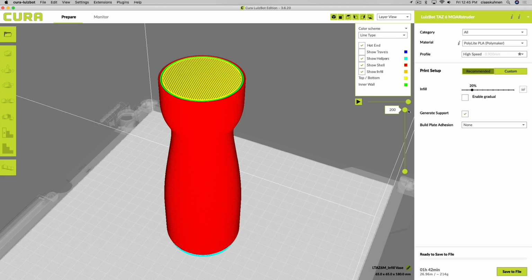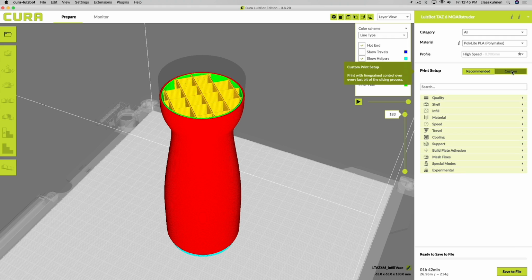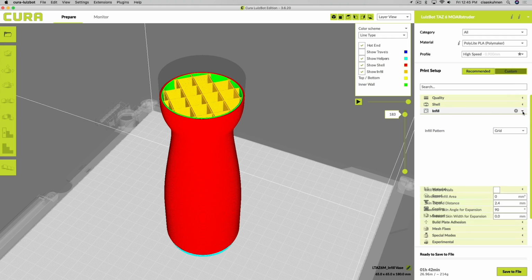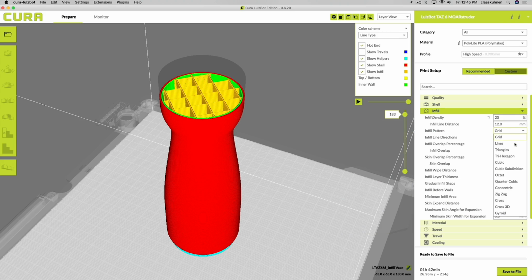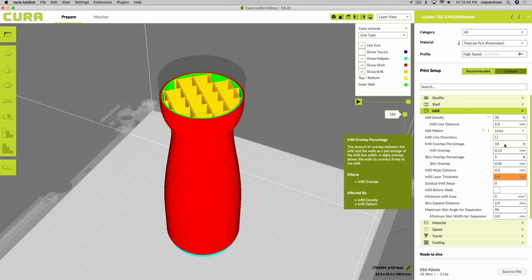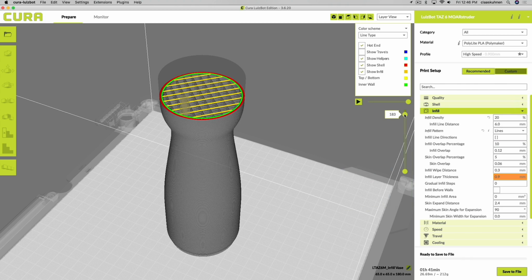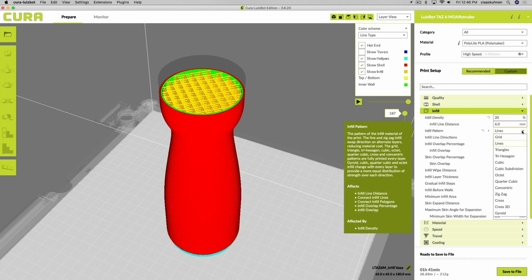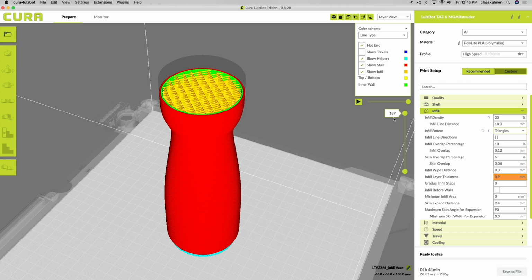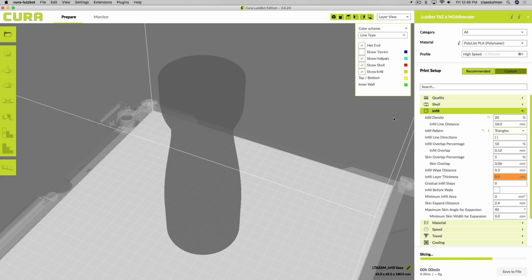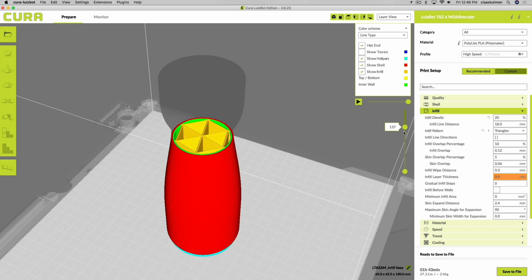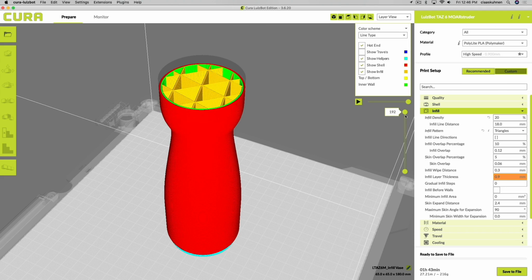The infill can also be customized. When we go to custom and infill, similar to support, also here I have various patterns I can select, and those will generate various structures. From my point of view, very often I go with the default values. I found them, to be honest, in 99% of cases, always working really well.